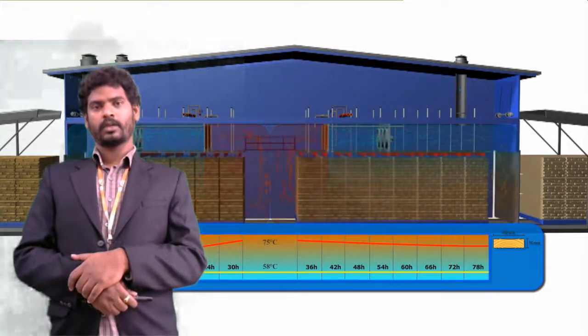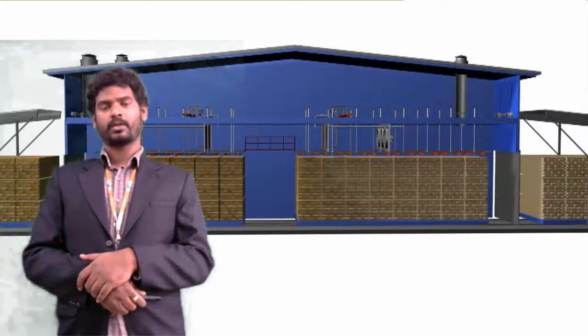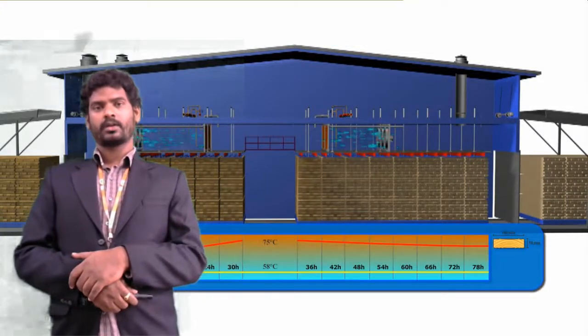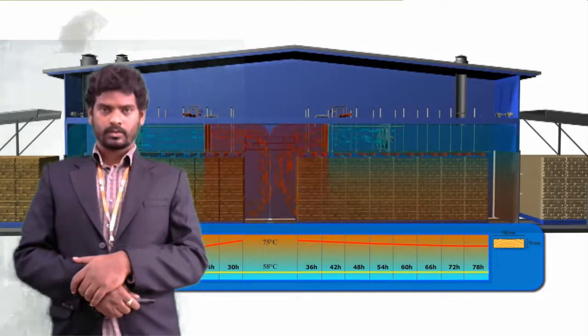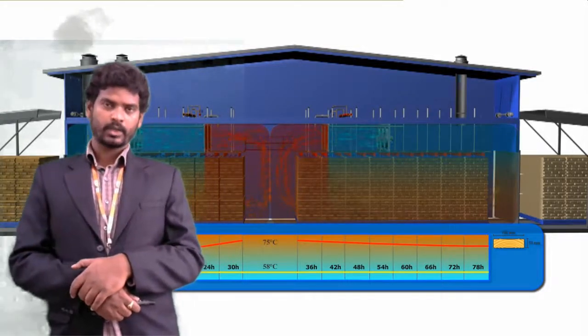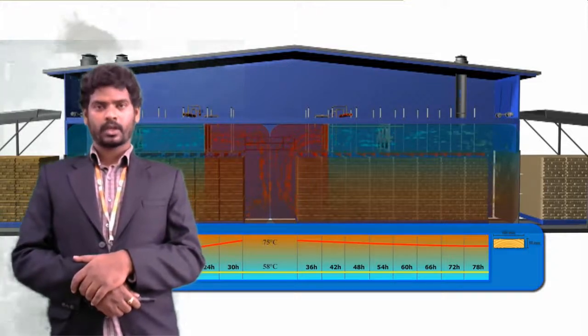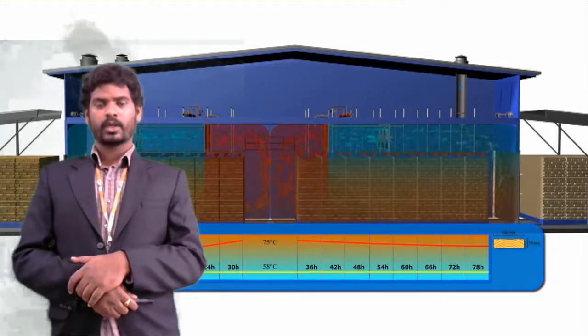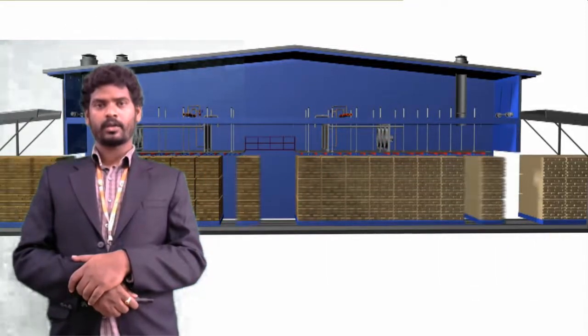The required humidity level is maintained to avoid warping and cracking. The drying of the timber at a uniform rate is maintained by circulating hot air by fans, and a certain amount of steam is added in order to retain correct humidity.